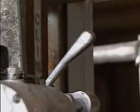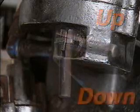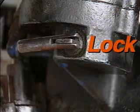The hoist mechanism is controlled by a hand lever that regulates the flow of compressed air, and by a directional control valve that has three basic positions: up to raise the scaffold, down to lower the scaffold, and lock to hold the scaffold in a particular position.